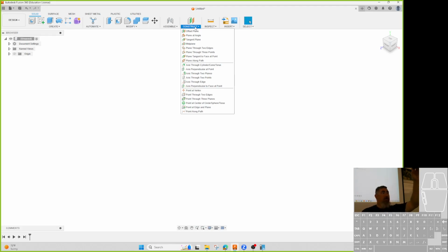Same thing with this one. If it's cutting straight through, depending on what angles are important, we could create a sketch here and loft between them. We could also just create a plane in the middle, draw our V, and extrude both ways to make the cut. And that way we can adjust the angle of the cut also. So maybe if it's not always a 45, maybe sometimes we want it steeper, we can adjust that with a plane that's angled through there.